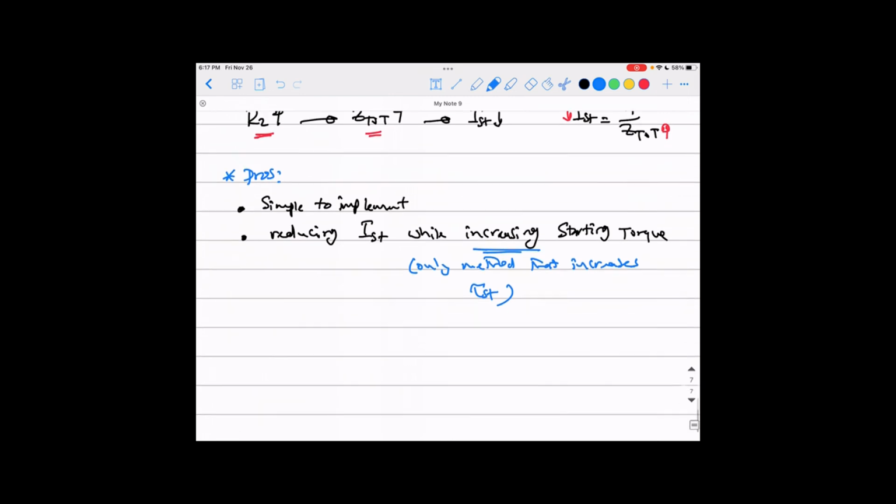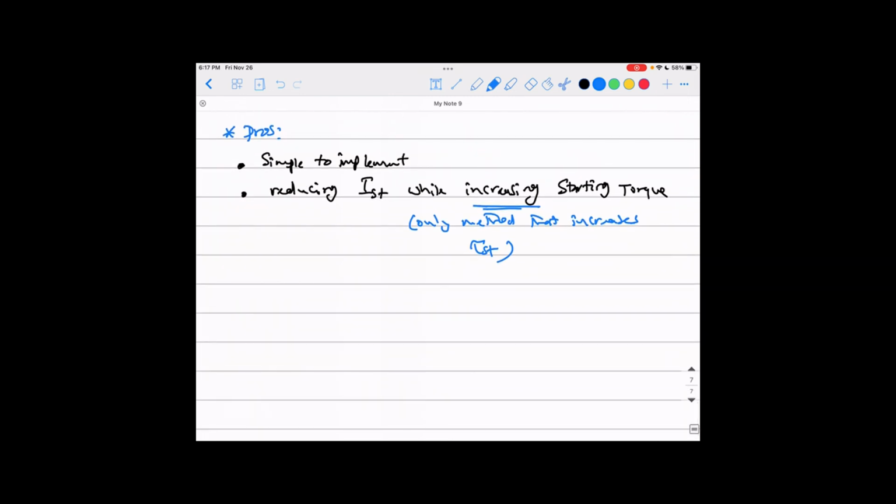Okay? How this happened, I can actually go with you for a little bit. Go back to our torque speed characteristic equation here. Okay? Remember, the torque of the motor equals 3 V Thevenin squared divided by (R Thevenin plus R2 over S) squared, plus (X2 plus X Thevenin) squared, multiplied by R2 divided by S omega S. Yep.